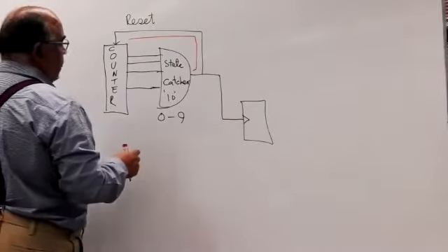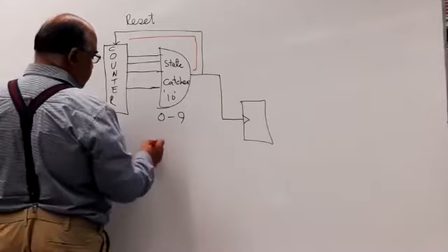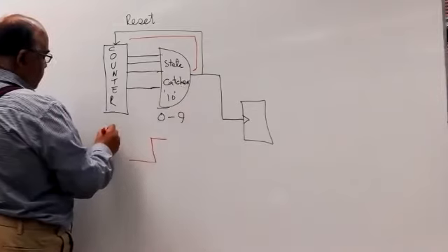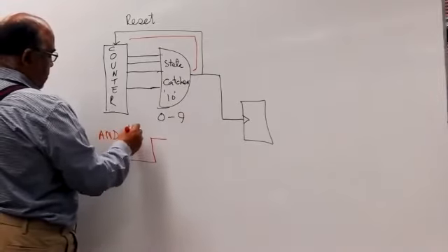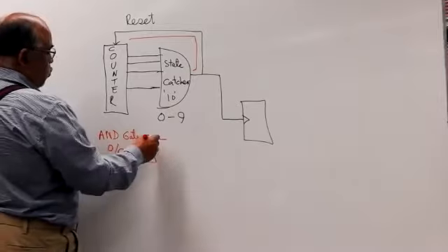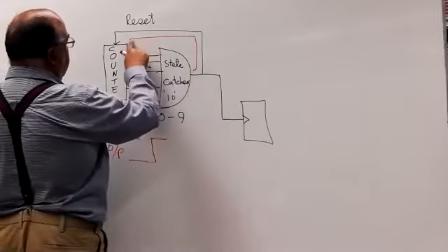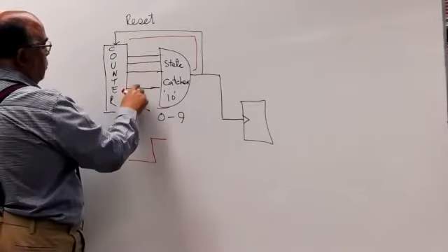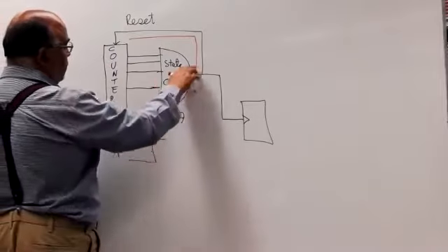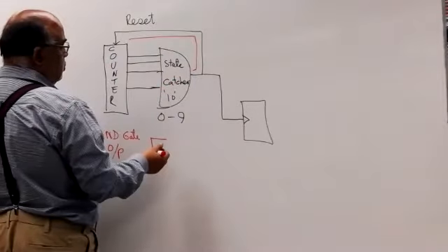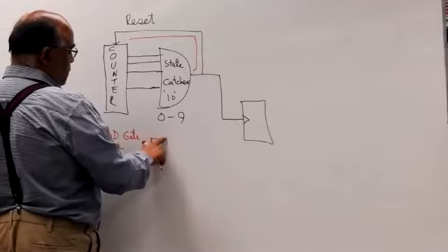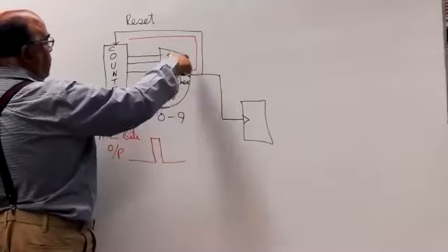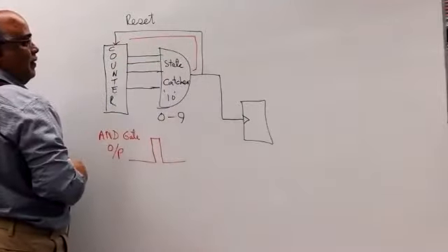Basically, what is going to happen is that as soon as this input becomes 10, the AND gate output will become 1. But as soon as it becomes 1, it will reset this counter. So the counter will become 0 0 0, and the 0 0 0 to the state catcher will return this output again to 0. So this is basically the round trip time of this circuit.